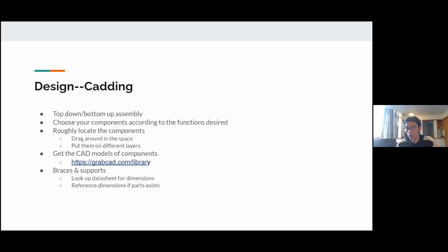So for example, the ultrasonic distance sensor kind of returns an analog value, but when it communicates with the Arduino, it actually only uses digital signals. And I also explained the reason. It is because it measures the time in between sending and receiving the ultrasonic wave, instead of any other magical method that just returns a distance. Yeah. So next I'm going to talk about the design of the robot.